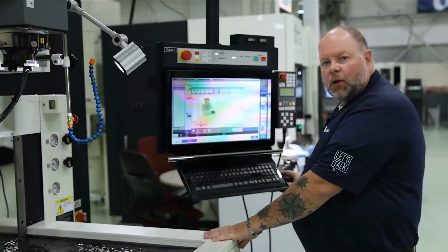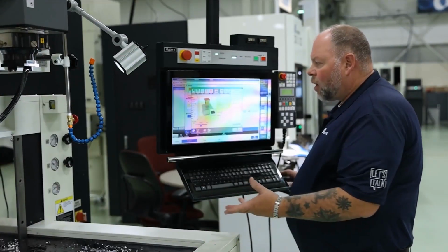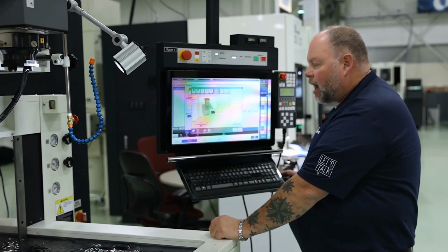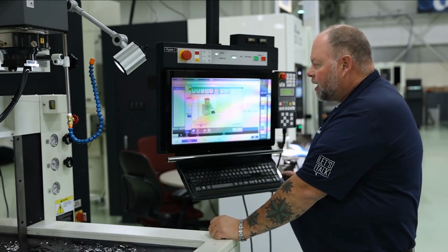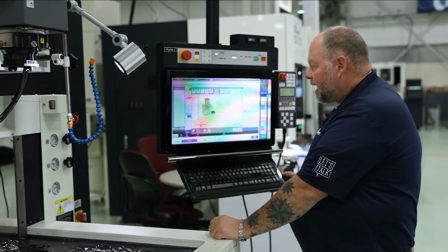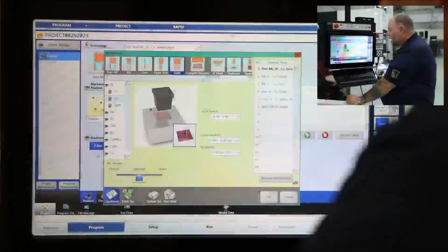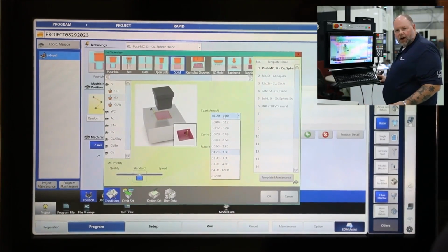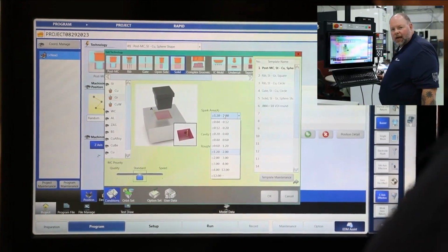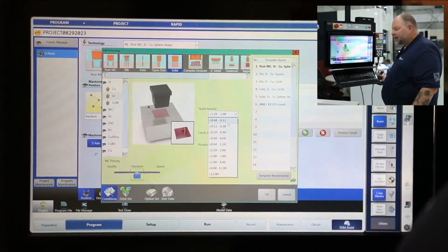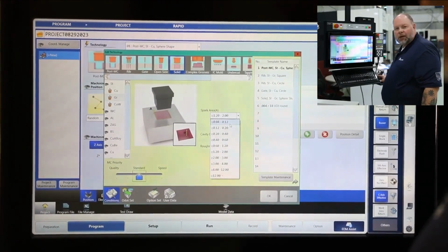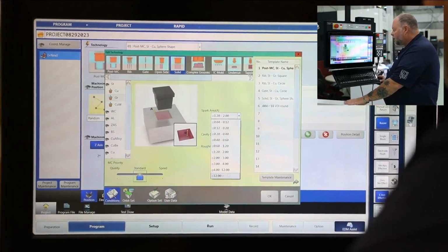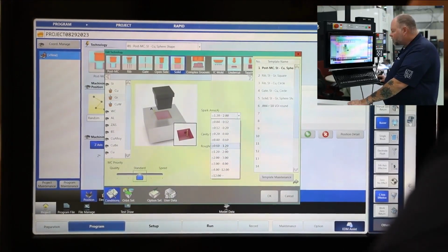Next, I'm going to select the workpiece material combination. So what type of electrode, and then what type of workpiece material as well. We're going to do steel, select steel, graphite to steel, go in and select our spark area. Spark area is the frontal contact area of the electrode. That's in ranges, so we have ranges anywhere from 40 thou up to 12 inches square, so very small to very large. I'm going to do a 1-inch square graphite electrode.